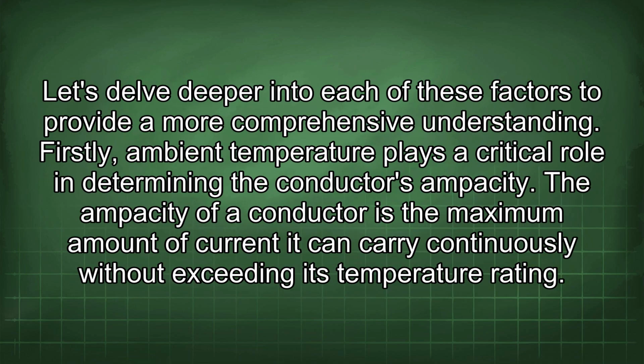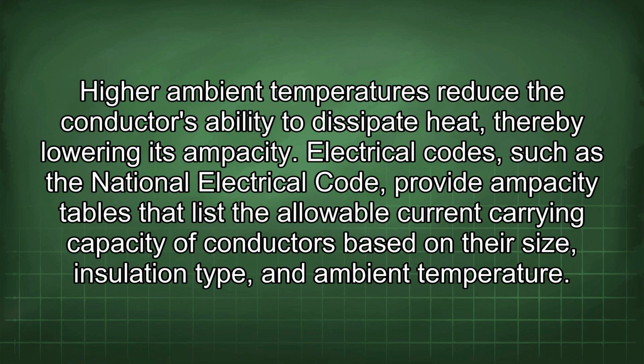Let's delve deeper into each of these factors to provide a more comprehensive understanding. Firstly, ambient temperature plays a critical role in determining the conductor's ampacity. The ampacity of a conductor is the maximum amount of current it can carry continuously without exceeding its temperature rating. Higher ambient temperatures reduce the conductor's ability to dissipate heat, thereby lowering its ampacity.